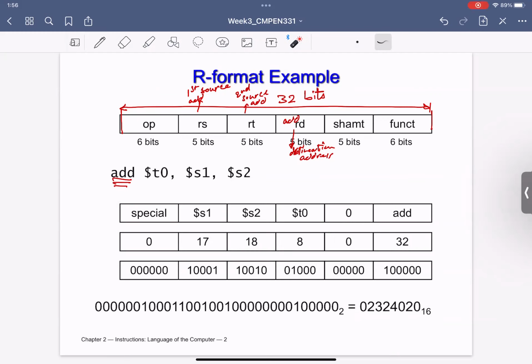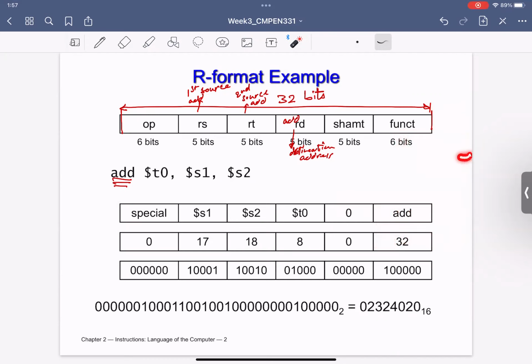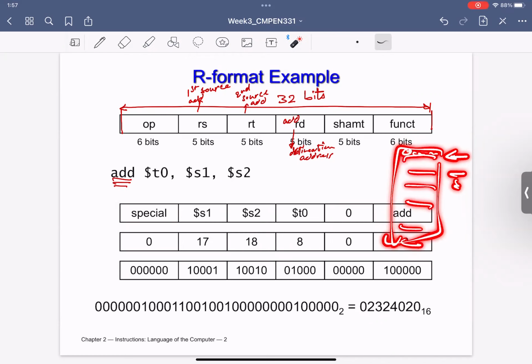Remember again that the problem here is that we have a register file. This register is 32 bits wide, and there are 32 different registers. I would like the CPU to know how it can address any of these registers, or if I would like to shift, how much I can shift in total of these 32 bits. So if you were to think about the number of bits needed for each of these instructions, how would you think about it?